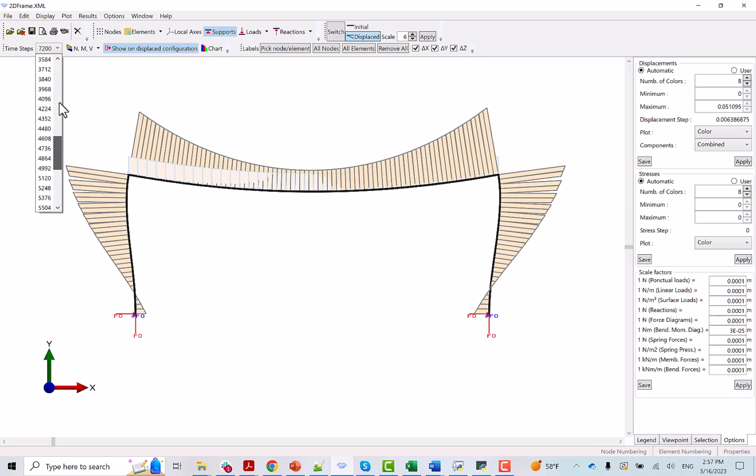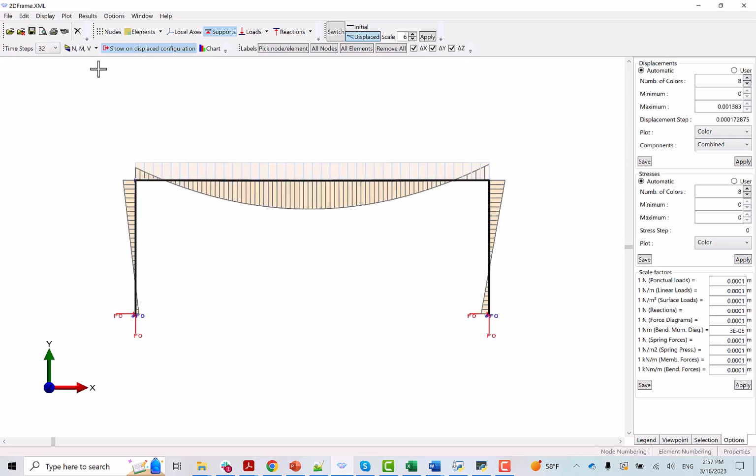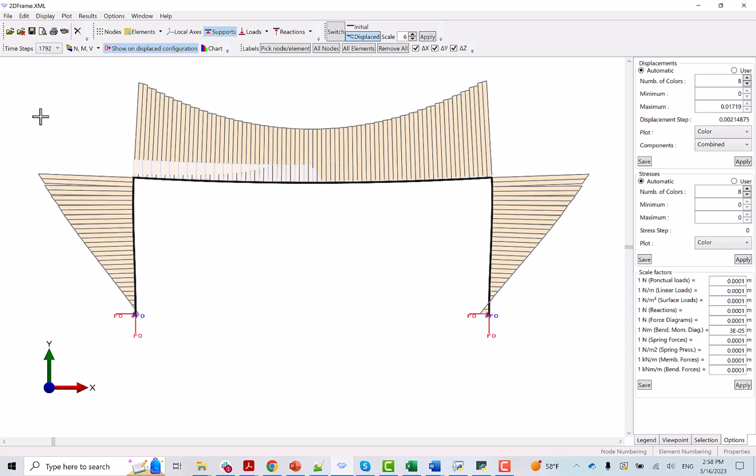Okay, so we see that initially under the applied load, we have lots of positive bending moment at mid-span of the beam, already for most of the span of the beam, but we do have continuity at the beam column connection. And as the temperature increases, and of course we have a temperature gradient because the sections are heated on 3 sides, so it creates a restrained curvature, and we have a negative bending moment that builds up due to this restrained curvature. And you see that now the beam is completely in negative bending.